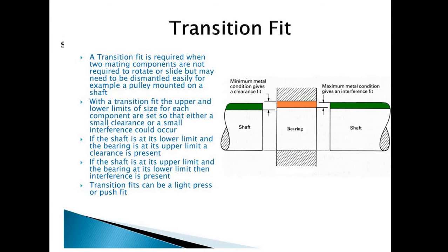The maximum size of the shaft, this distance from here to here, is going to be larger than the minimum size of the hole. So this distance is always larger than this distance. If this condition is there, then you can say that this is the case of the transition fit.